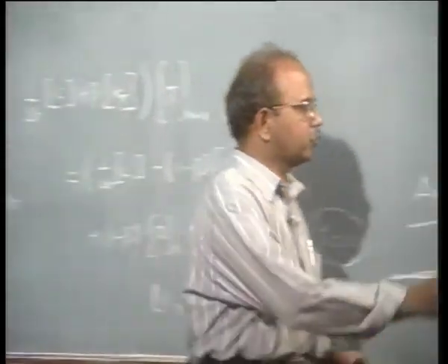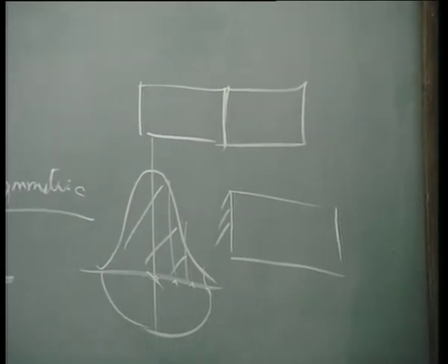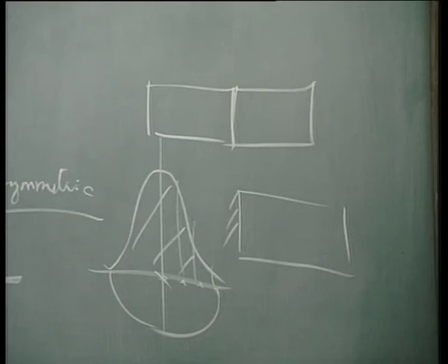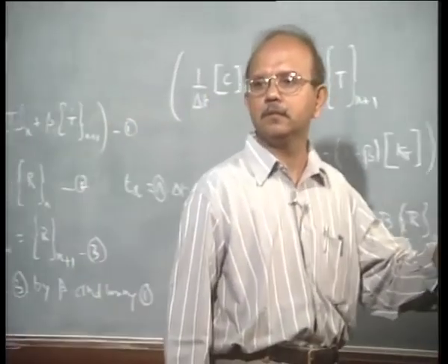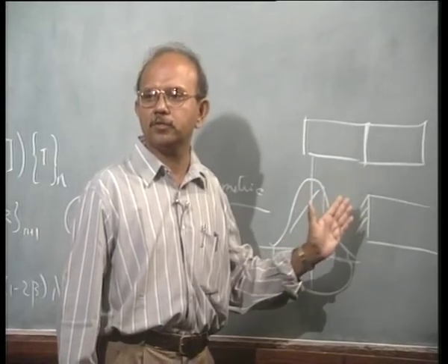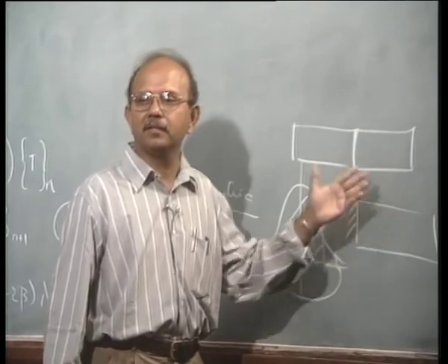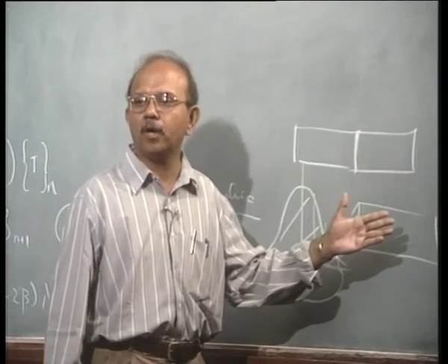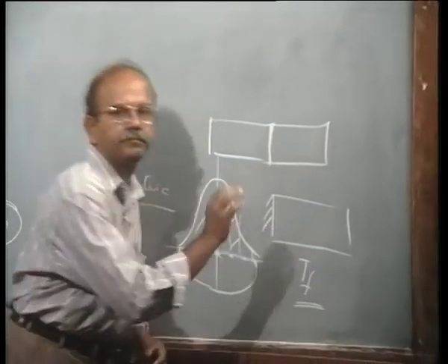There is no heat transfer in that region. We say that initially both of them are touching and that there is no heat transfer in that region because we have a symmetry about this line. So, no heat transfer in this position. We do not anywhere mention the temperature as in heat transfer boundary condition, but what we mention is the temperature of the fluid outside, Tf outside, right.